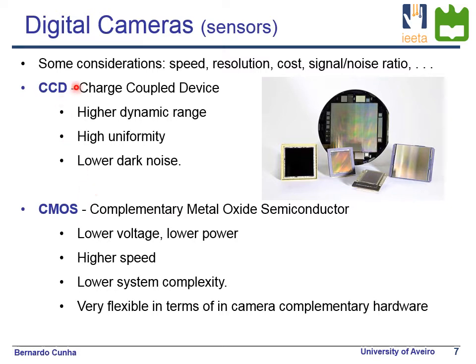Nevertheless, the fact is that CCD is the kind of technology which is used less and less because the overall cost of this technology is typically higher than the one you get with CMOS. So you would select a CCD technology for very particular cameras. If you require, for instance, very high resolution color images, where you probably would use not one sensor but three sensors, where the image will be split by a prism and projected in three sensors, where each one will have its own color filter.